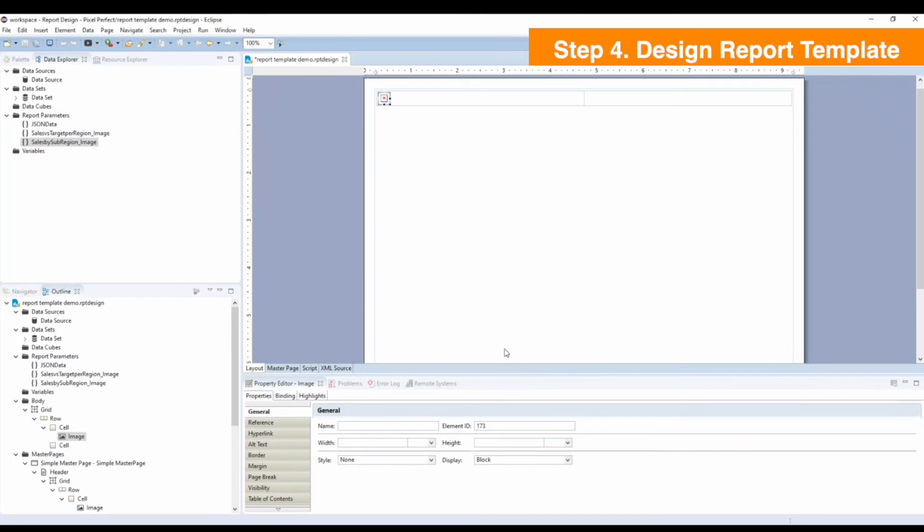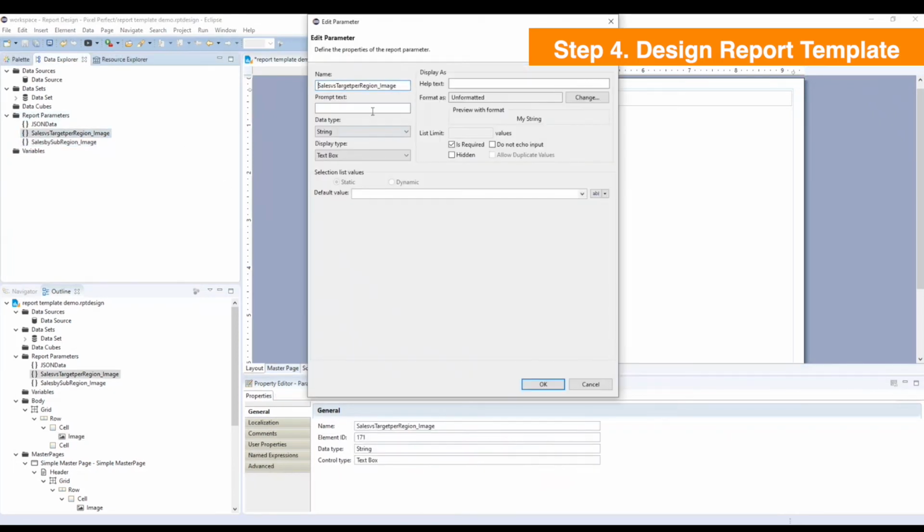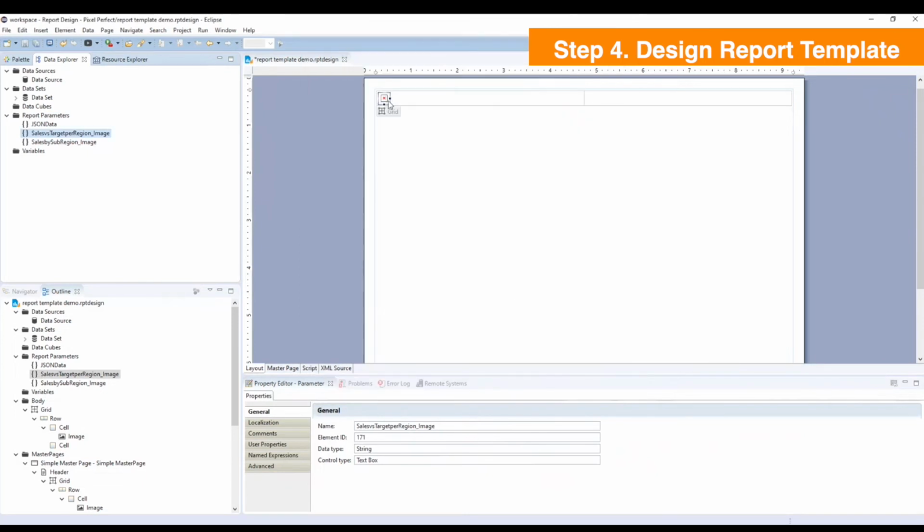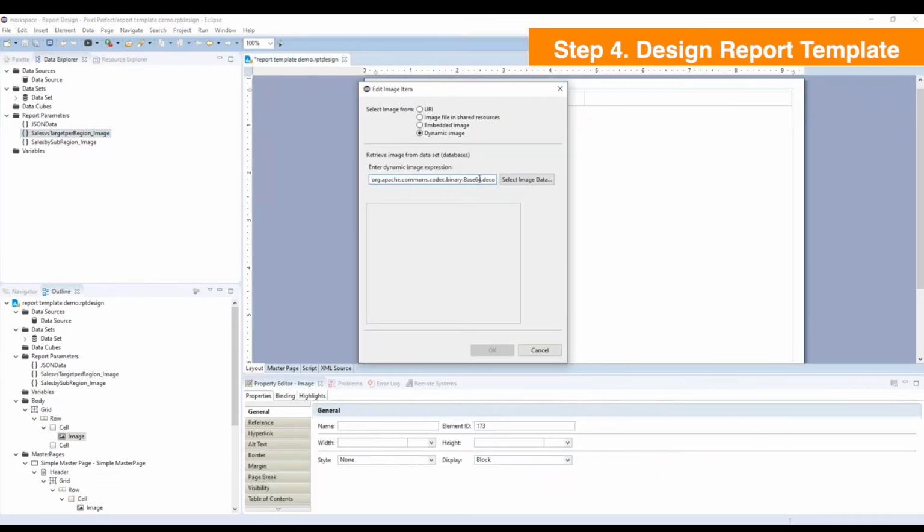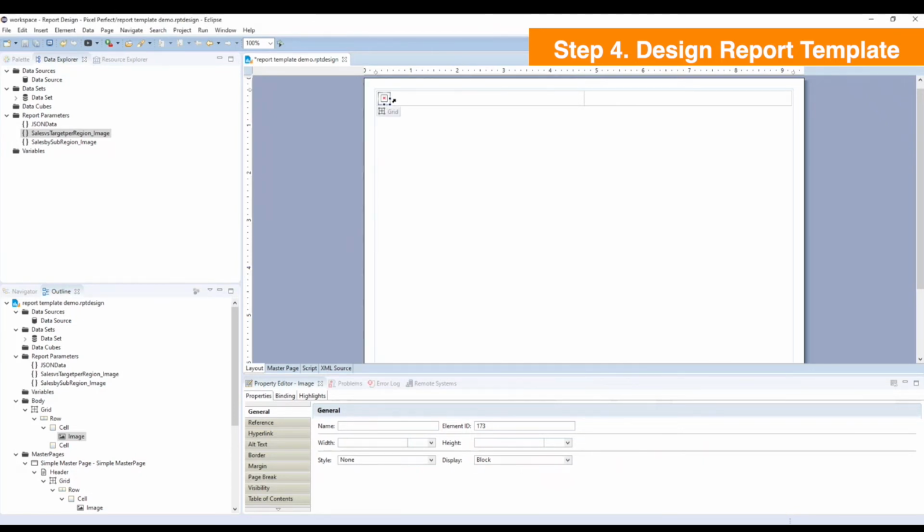So let's click on insert, copy the first parameter name, then double click on the image, navigate to the end and replace the sheet name _image by the parameter name. Let's click on OK. So now the image is inserted. Let's repeat the same process for the other image.